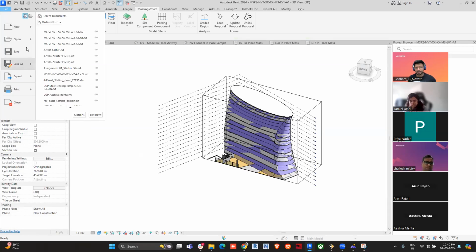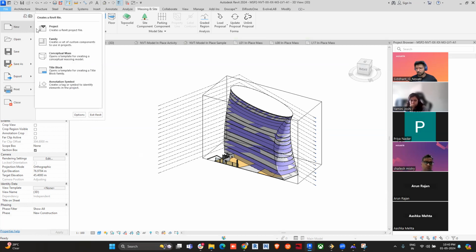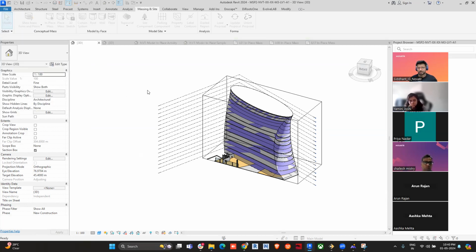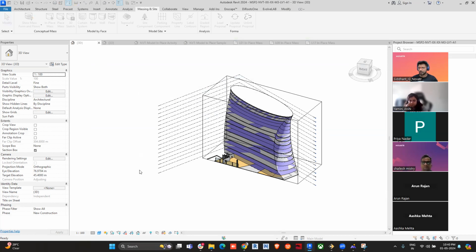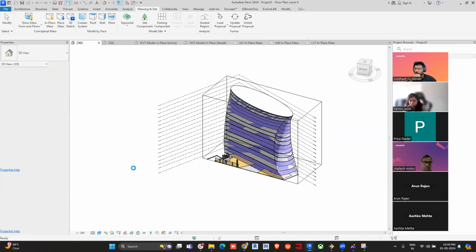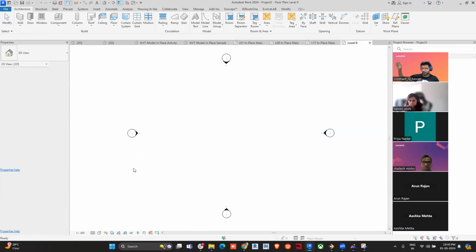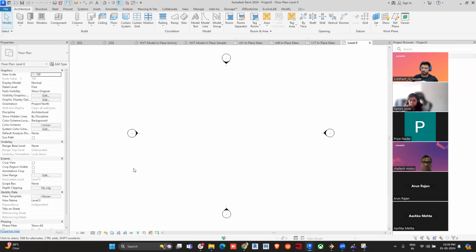I feel it's very important to understand the reference plane first, because it's like a canvas on which you can draw anything, right? I know in SketchUp you can just draw anything out of nowhere, on any space, but in Revit it's a bit different. You need to assign some plane on which you can draw. I mean, it simplifies the modeling process, right?